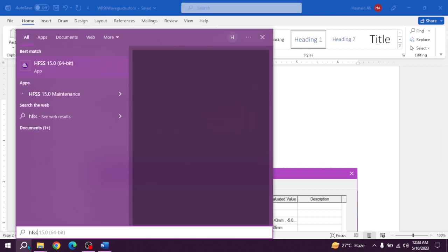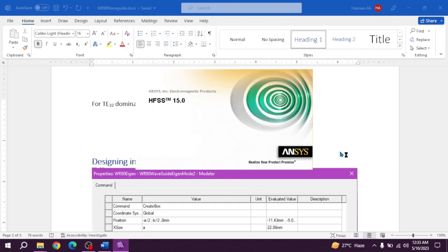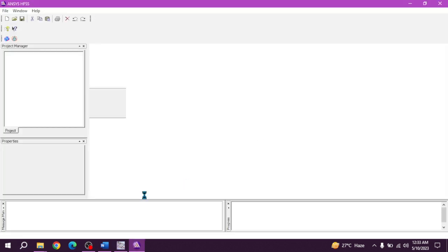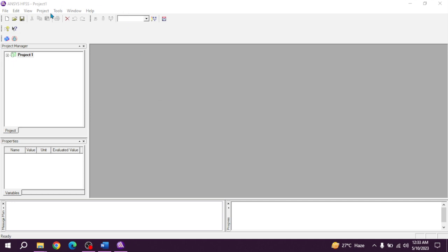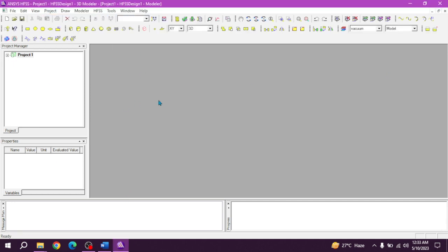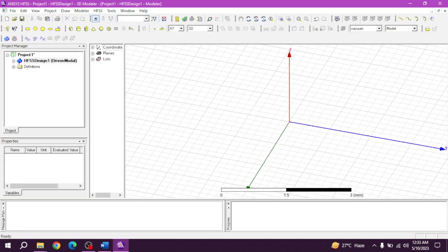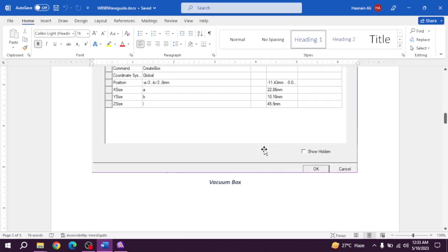So I will open HFSS. Insert HFSS design project. At first we will create a vacuum box.